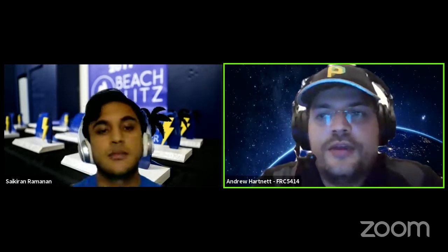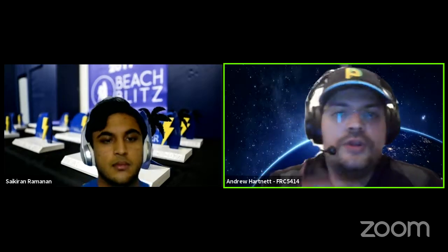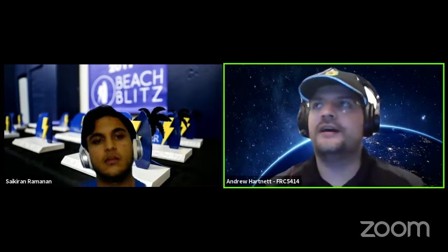Awesome. Another question we got was, does the software provide recommendations on resistors and capacitors, like when they should be used between components? No. What Altium will help you do is you can do a search and find out, through the manufacturer part search or the integrated devices, sometimes what some different values are readily available. But all the design stuff is stuff that you have to do outside of Altium. The real electrical engineering work is looking in data sheets, which is a big thing. A lot of times data sheets, especially if it really matters, will have suggested